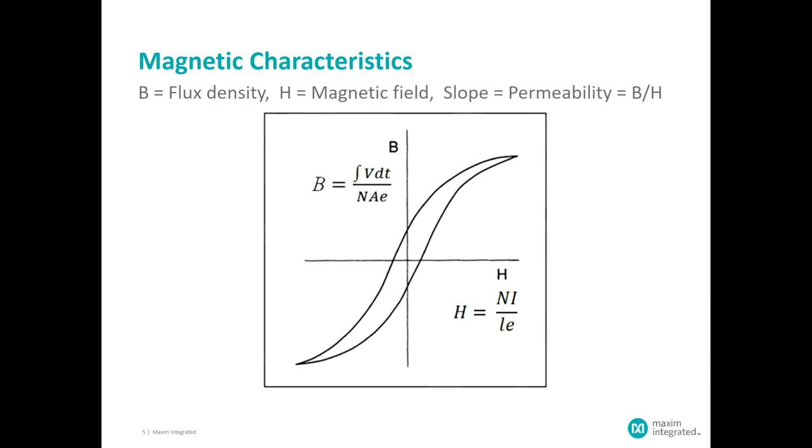And materials that have an excellent magnetic characteristic, a high degree of magnetism capability, would have a high permeability, and that curve would be very vertical, meaning that a very small amount of current would give you a very large flux density. The net result of that is that permeability and the slope of that curve is related then to the storage capability.